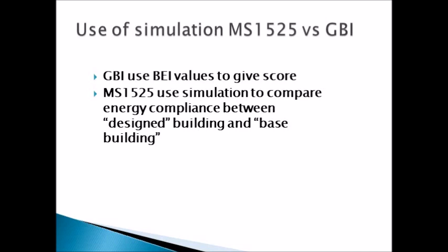So if the energy use of your design building matches that of the base building, which is the one that uses the specification as required in MS1525, if they match, then you are okay to go. Otherwise, if your design building uses more energy than the base building, then you have options of mitigating the energy use by using daylighting, by using better equipment than the minimum requirement, that you have to spend a bit more on your design building to achieve similar